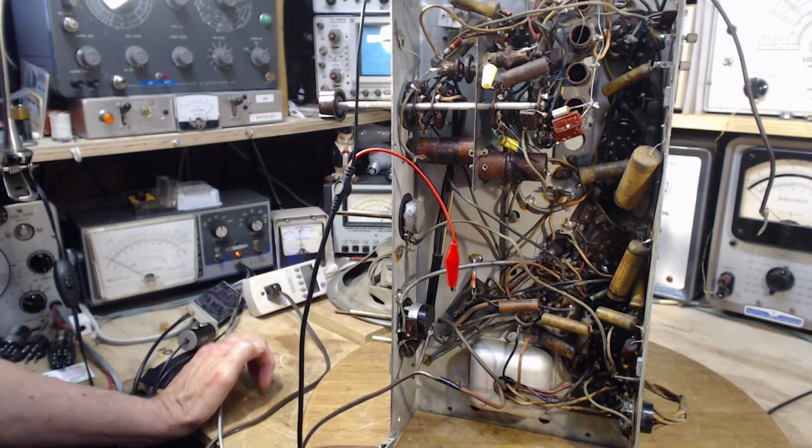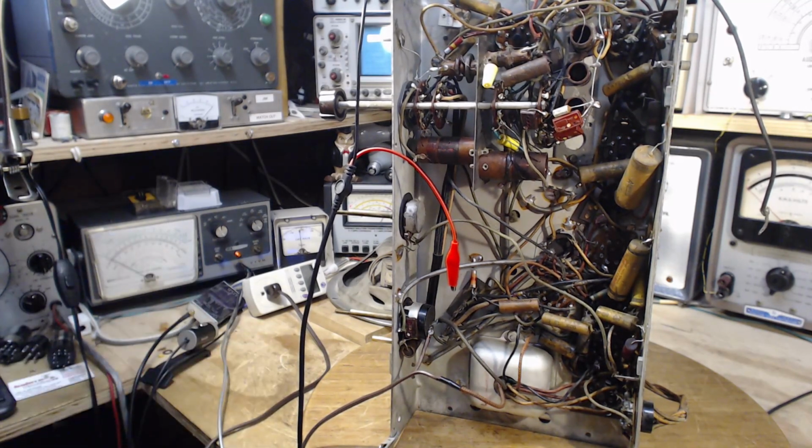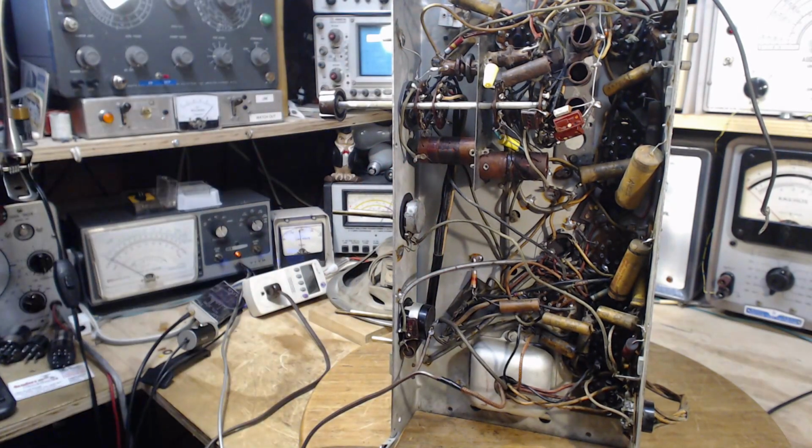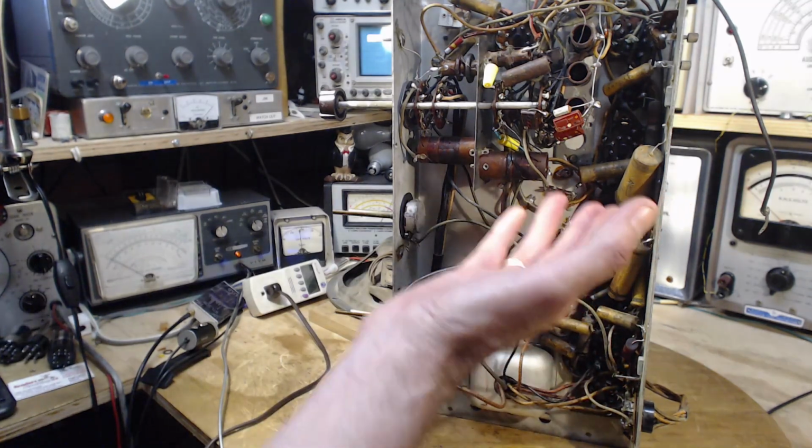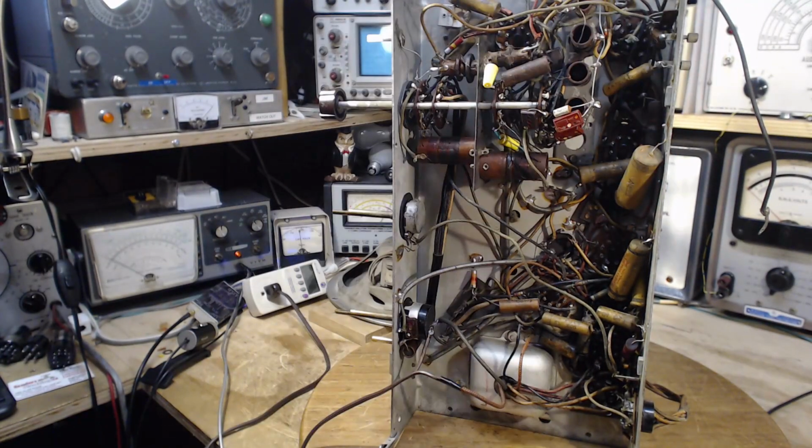Okay, so we've eliminated the local oscillator as being any kind of performance-causing problem, but we've identified alignment as being out on this radio. Out. Needs attention. Okay, so the name of the game from here forward is we're just getting back to changing out capacitors, and we'll change them out up here and just check the radio periodically as we're doing this. Ultimately see what happens. But that's the end of today's efforts here.